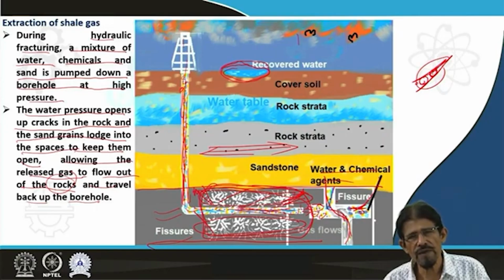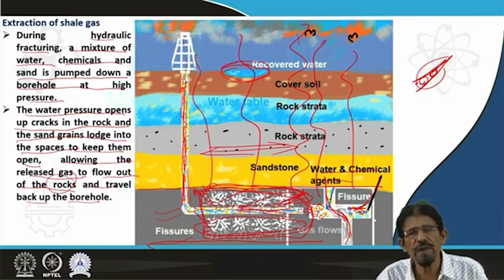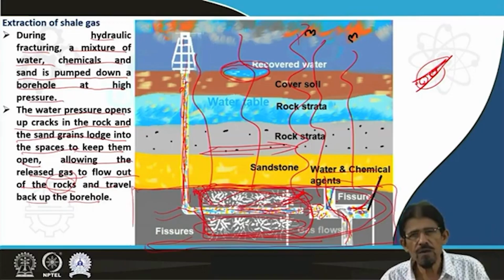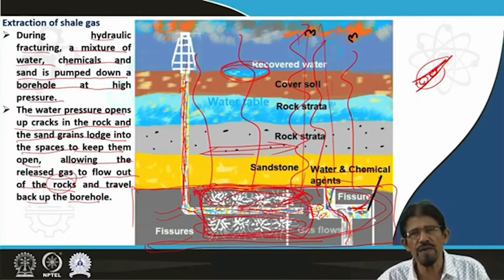Due to hydraulic fracturing, these discontinuities also become a site for bursts of mechanical energy which come in the form of P and S waves, and which are responsible for vibrational effects and sometimes may also cause earthquakes of moderate magnitude. On another side, due to continuous change in permeability, porosity and release of gases, this strata is not suitable to hold the overlying weight of the strata as it did earlier.